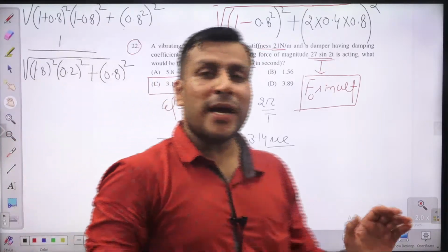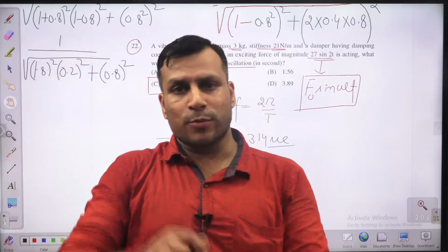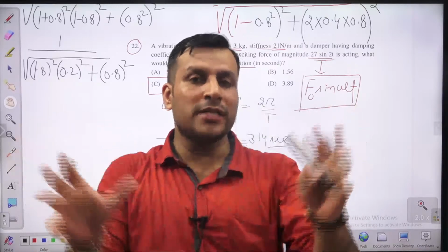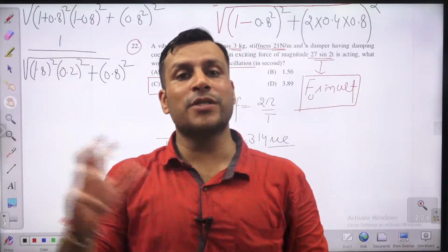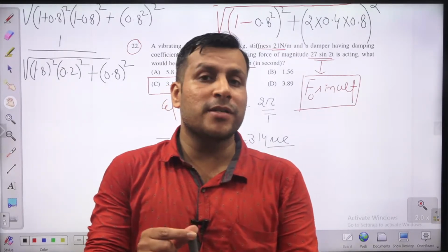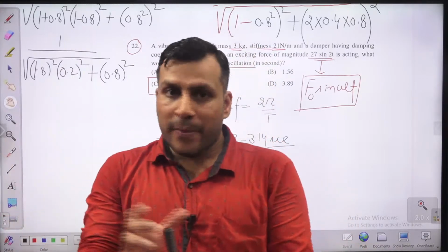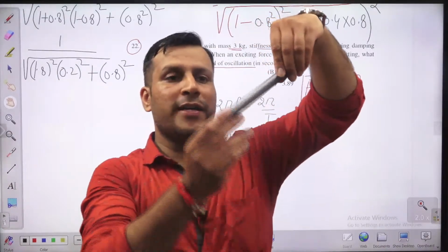What I mentioned, guys, why I'm not considering natural frequency? Under the influence of the external force, the body is not going to vibrate at natural frequency. Like suppose there is a lathe machine and some motor is attached over that. So whatever the components are, they are going to vibrate at the frequency of the external excitation. So in case of forced vibration, the body is going to vibrate at the frequency of the external excitation.